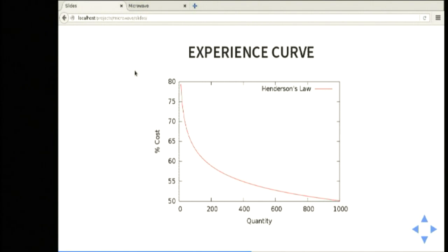So the idea is that if you make one unit, the price of one unit allows you to determine the price of, say, 1,000 units, because it follows a relatively well-known scale as you build more, and the price of one unit is determined by the complexity of the board, which is why everything that's complex I'm just going to buy, and anything that I'm planning on designing is very, very simple, sort of 3 or 4 components.